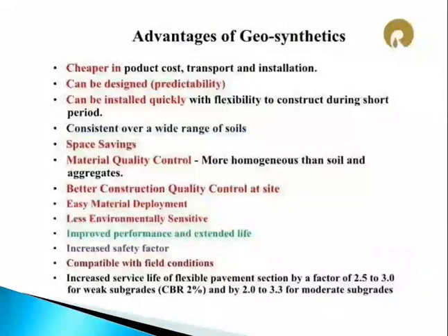So advantages of geosynthetics: cheaper in product cost, transport and installation, can be designed predictably according to requirement. You can design it, can be installed quickly with the flexibility to construct during a short period. Consistent over a wide range of soil, space saving, material quality control, more homogeneous than soil and aggregates, better construction quality control at site, easy material deployment, less environment sensitive, improved performance and extended life, increased safety factor,